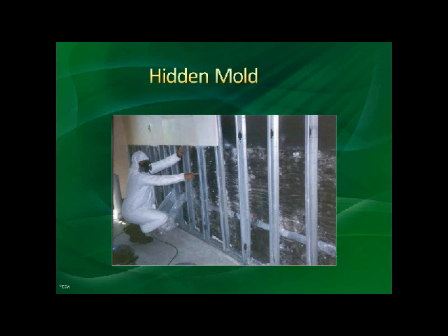This is an idea of what happens. Can mold grow behind the walls and never show through on the actual side that you're looking at? Yes. It can grow between the walls in immense proportions. It can grow behind wallpaper. This is why moisture meters around windows or doing thermal imaging is so important.